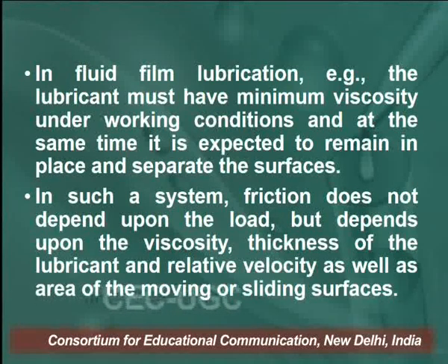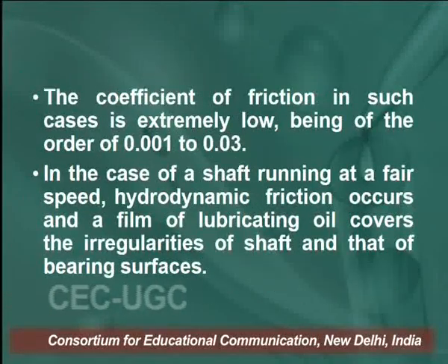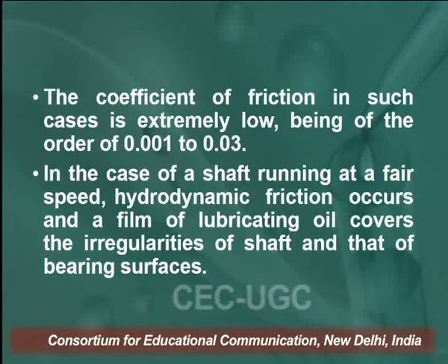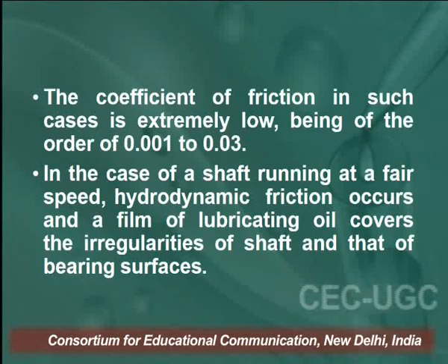In such a system, friction does not depend upon the load but depends upon the viscosity, thickness of the lubricant and relative velocity as well as the area of the moving or sliding surfaces. The coefficient of friction in such cases is extremely low, being of the order of 0.001 to 0.03.